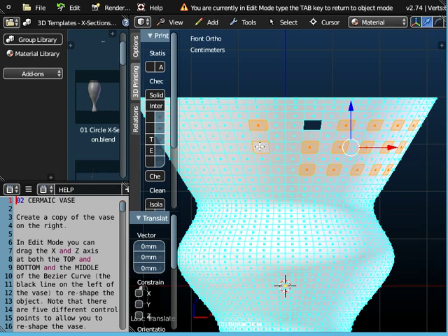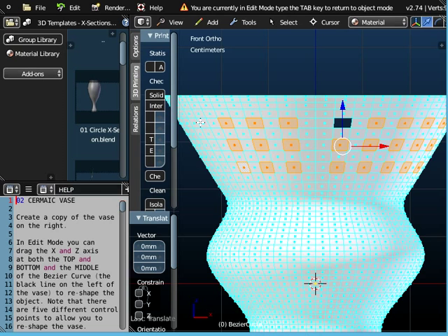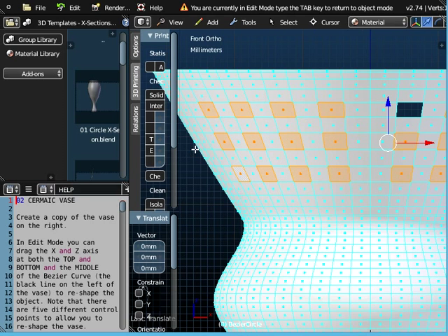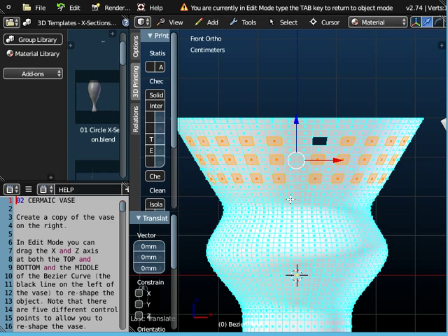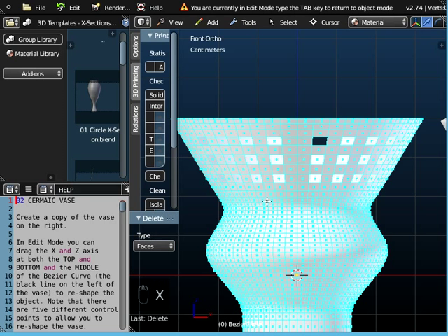I want to do the same on the other side. So I want to start there and work my way out to the left, highlighting faces that are all one apart. I think I need at least one more row. Have I got enough? See, I've got 1, 2, 3, 4, 5, 1, 2, 3, 4. So I still want to do one more lot on this side. So I'll just zoom in. Okay, so I've highlighted a pattern of faces, and it's X to delete the faces.